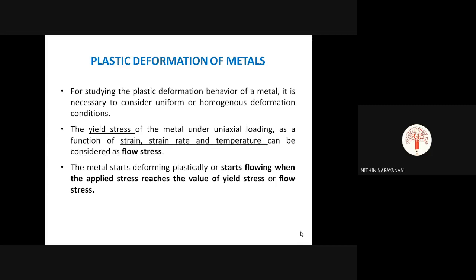So there are two types of stresses. One is axial stress, the second is shear stress. Axial stress is produced because of an axial or uniaxial load, and it is perpendicular to the cross-sectional area. Shear stress is parallel to the plane of the area. This axial stress can be a tensile stress or a compressive stress, and shear stress can be in different planes. It can act parallel to the plane.